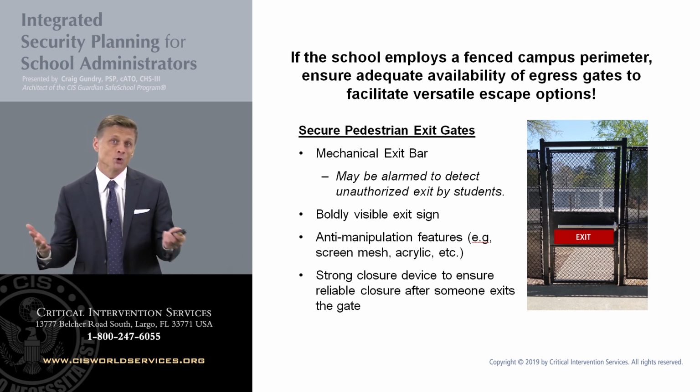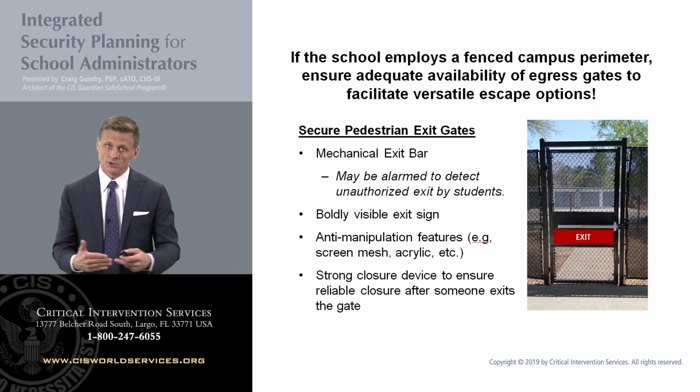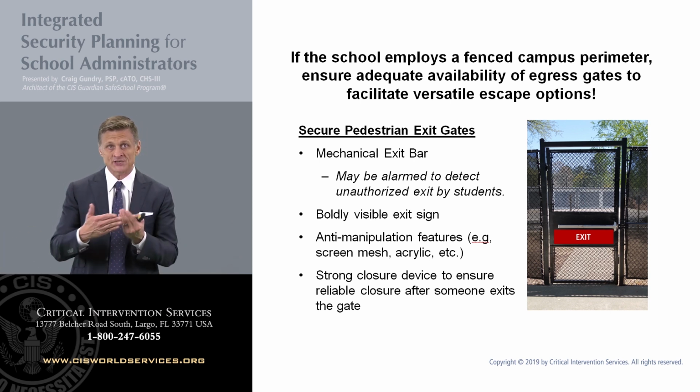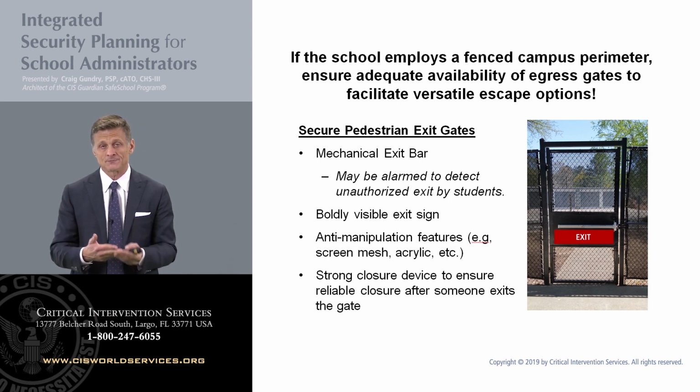And that in the real world is a common thing that I've seen in a number of fenced campuses, is that over time the spring closure will often weaken, and as a result somebody exits out that gate, the gate just falls back and then sits without fully engaging the latch.